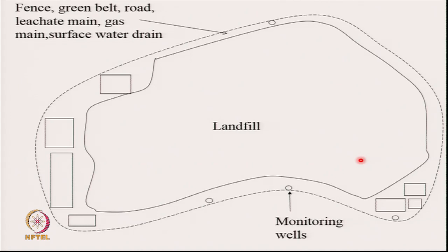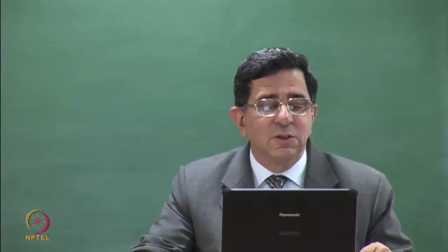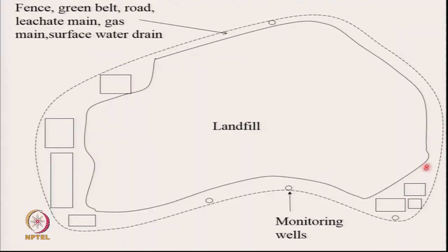So between what I've already taught you, that 80% or more is the landfill area. So the shape of the landfill has now emerged like this. Agreed? And this shape is primarily governed by the outline and where I'm going to put the facilities. So entry and weighbridge, office buildings, laboratories, treatment facilities. And since the groundwater flow direction is in this way, I'm putting an upstream monitoring well and 3 downstream monitoring wells here.